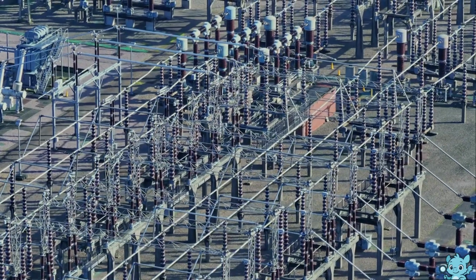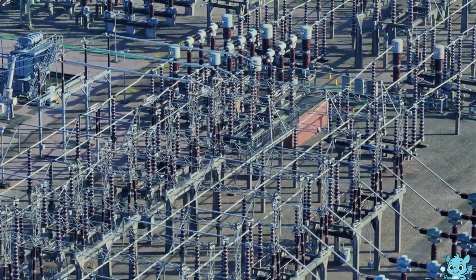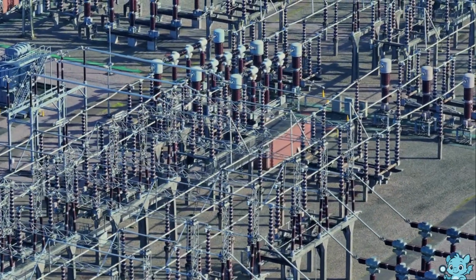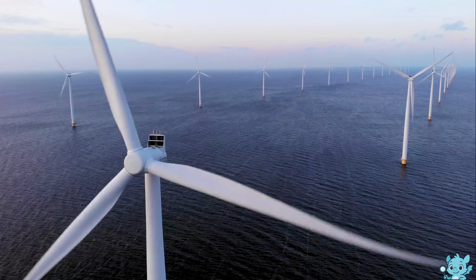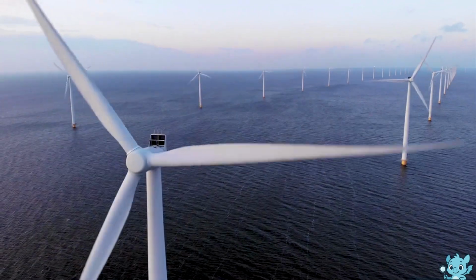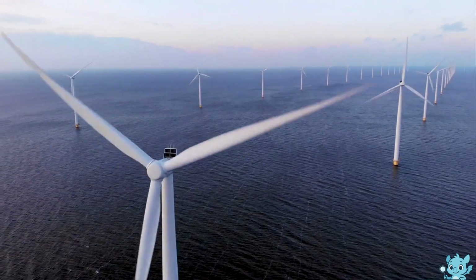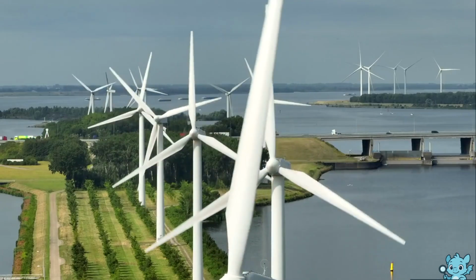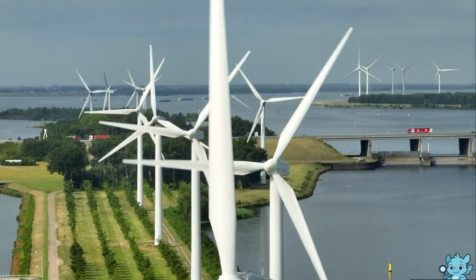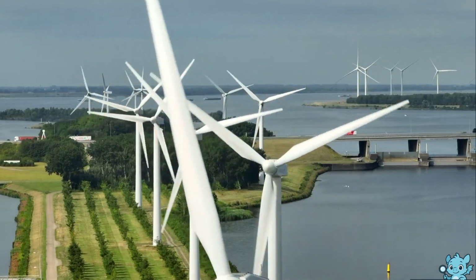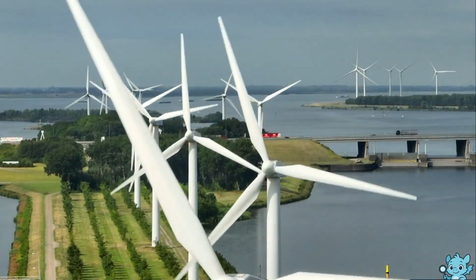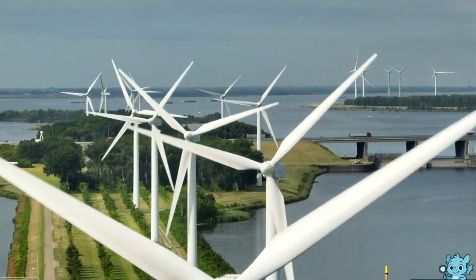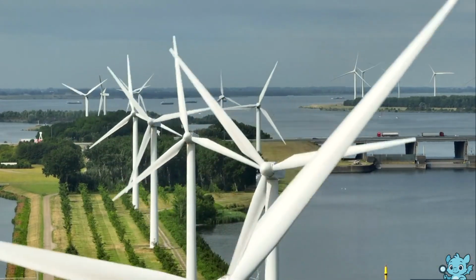Before the electricity can be sent to the grid, it must be processed by a power electronics system to ensure that the power is compatible with the grid's voltage and frequency. Most modern turbines use sophisticated control systems to regulate the power output and adjust the turbine's operation in real time. Inverters and rectifiers. If the turbine uses variable speed generators, the control system may include an inverter or rectifier to convert the varying output into a steady stream of alternating current electricity.